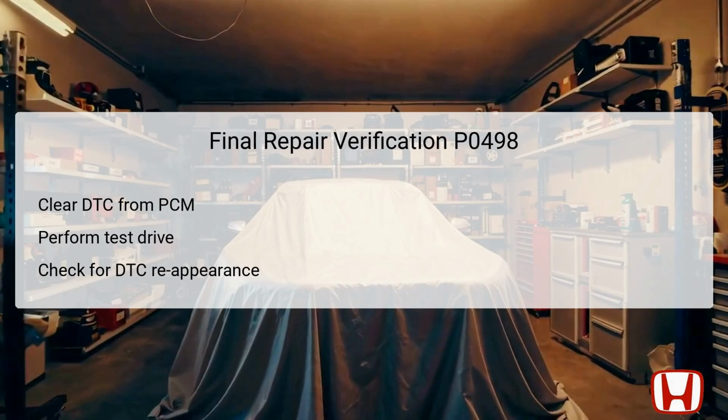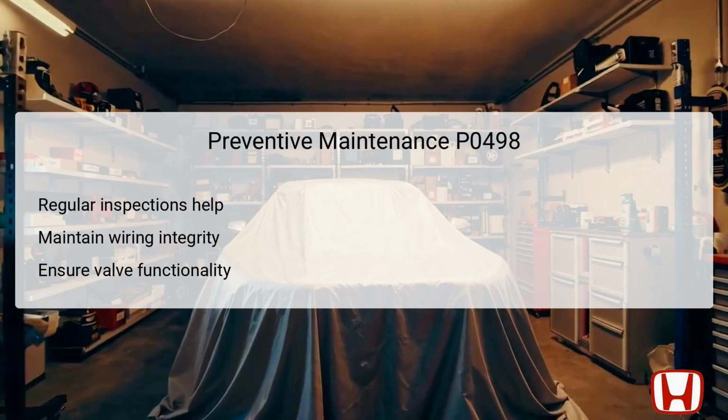After completing the test drive, reconnect the diagnostic tool to verify if DTC P0498 or any other related codes reappear. Successfully completing this verification will ensure that the vehicle is operating as intended without recurring issues. To prevent the recurrence of DTC P0498 and ensure the emission control system remains functional, regular maintenance checks are imperative.